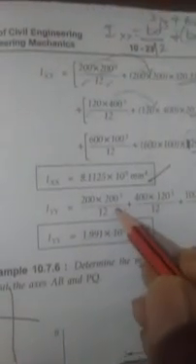Consider the center of the first section lying here, then the distance from here to here would be d, but here the centroid lies exactly on the same line. So if you fold like this, in which direction it is symmetric, d will become 0. You have to keep it in your mind: if it is symmetric about the x-axis, in the IYY d will become 0. So it will be 200 into 200 cube divided by 12.